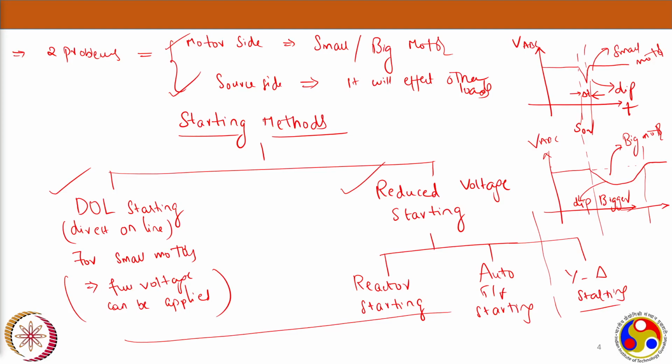So yeah, that's a simple trick, right? If you reduce the voltage at the input during the starting, it will not draw that much current, the 8 times the rated current, because it will go down drastically if your input voltage is not full voltage. So that's okay. But one condition: if you remember the previous week's discussion, when we were inserting resistances in the rotor circuit, we introduced external resistances in the rotor circuit and saw that the starting torque improved. I hope you all remember that discussion.